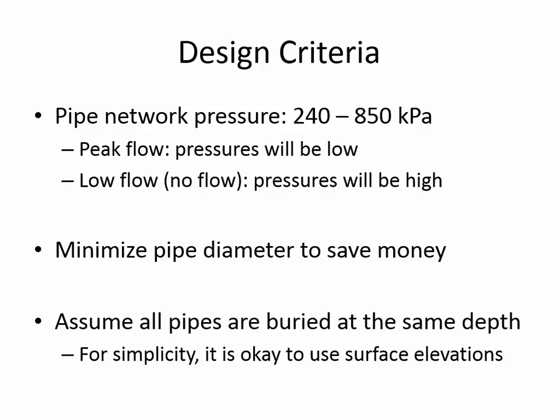And so you won't actually be telling it how big the tank is in WaterGems. You'll just be saying there's some infinitely large reservoir that has a water surface elevation of X. So what you maybe should do is say, I assume that the tank is going to go here on the map, and the water level will be maybe 1 meter deep. Worst case scenario is that not only is this the day when there's a fire and everyone's watering their lawns and there's a football game, but also the reservoir is really low.